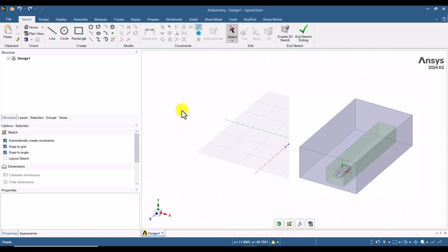But upon this, I'm going to draw another zone which is not subtracted. It's an independent part, which helps us later in Ansys Meshing to have more accurate element distribution behind the vehicle. Because this is going to help us decrease the computational costs.